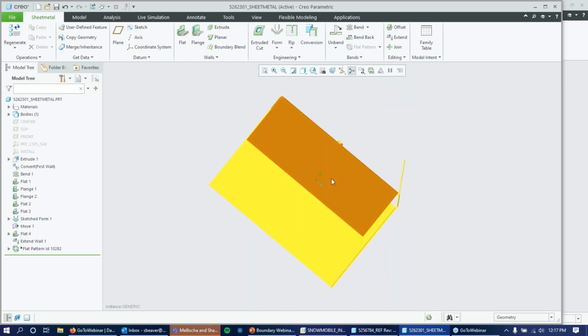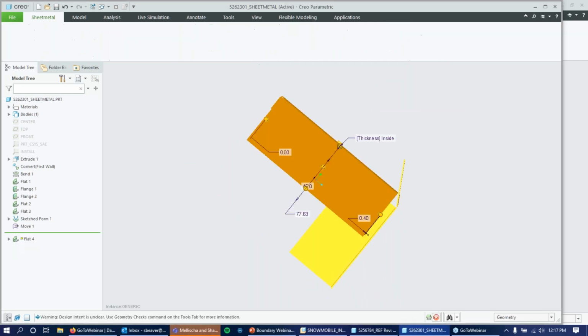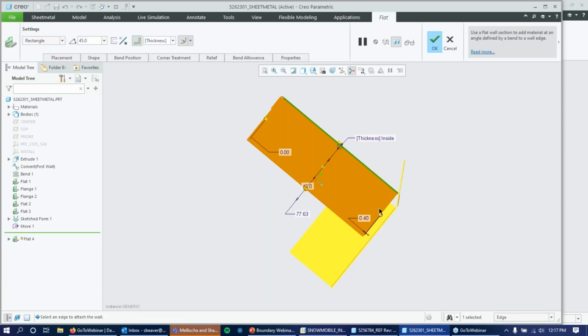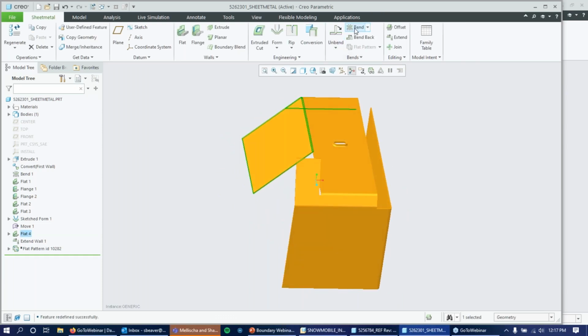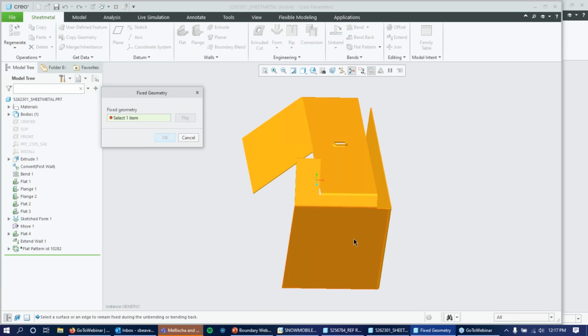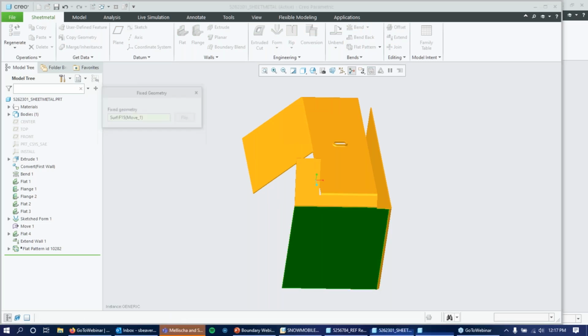So now what I'm going to do, just going to select this wall, edit definition real quick, deal with a bit of a load time, and then I'm just going to drag this over to the left, and we're going to see what happens when there's no overlap. All right, so now if I enable flat pattern preview here, I'm going to do that same fixed surface.